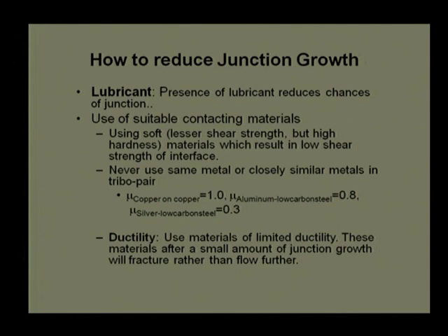Now, how to reduce the junction growth? I have noted down a few suggestions. Not necessarily everything will work in one situation, but one of the suggestions will work to reduce the junction growth. If you really want to reduce the junction growth, do not think about dry lubrication. Provide some sort of lubricant, either powder lubrication, solid lubrication, semi-solid lubrication, or liquid lubrication, which reduces the interface shear strength between the two surfaces.